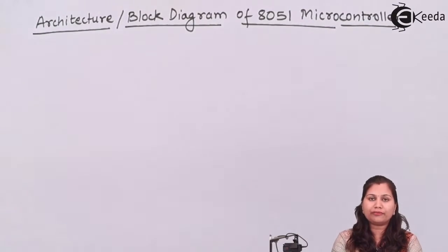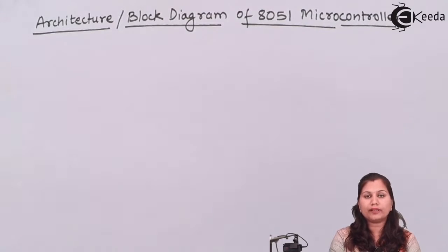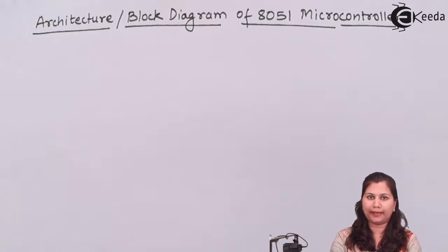The 8051 microcontroller is one of the most popular general purpose microcontrollers, which was designed by Intel in the 1980s. It is an 8-bit microcontroller, meaning it deals with data which is of 8 bits. It has a 40-pin IC, and it operates at a +5 volt power supply.